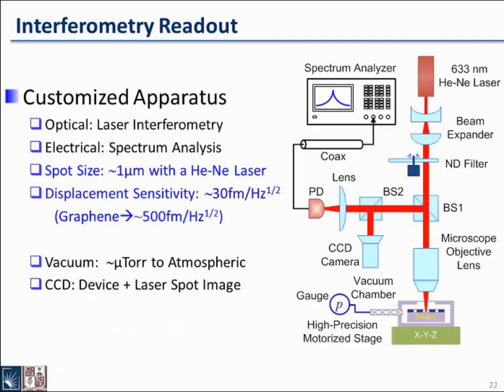And second is, once we put the mechanical resonance in electrical or optical circuitry, we can build a clock-like system that gives us the capability to sense or transduce something in real time, which is not readily done in a transistor mode. For a transistor electronic sensor, you really have to sweep the IV curve to figure it out. So that's a slow measurement.